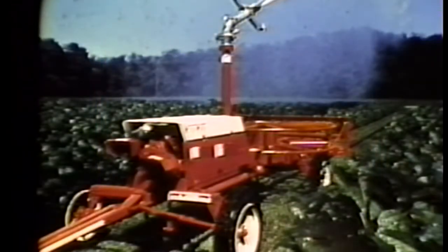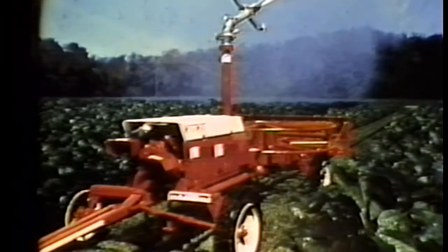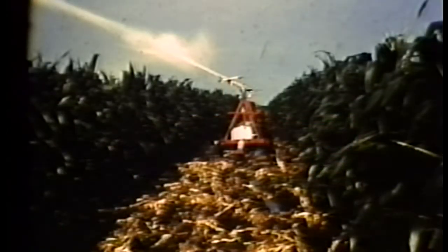The traveling sprinkler is a self-propelled type of system that moves continuously from one end of the field to another under its own power while sprinkling, using a big gun sprinkler to spray out the water. The cable tow traveler uses a flexible hose lateral which is dragged across the field by the same power that propels the sprinkler down the travel lane. The power is generated by a water-driven turbine.